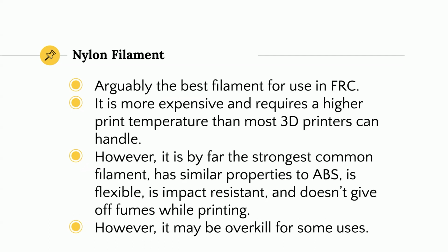Essentially, this is the only 3D printed material which I would truly trust to be using on very important mechanical parts on a robot. However, it may be overkill for some uses. If you're using nylon for some decorative part or some part that doesn't need to be very strong, I don't know why you're doing it. You're just going through pain and suffering and a lot of money for no particular reason.